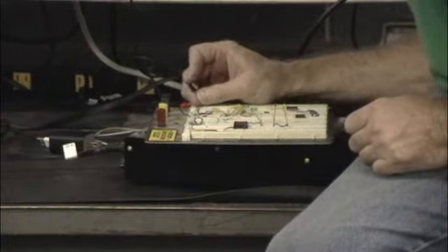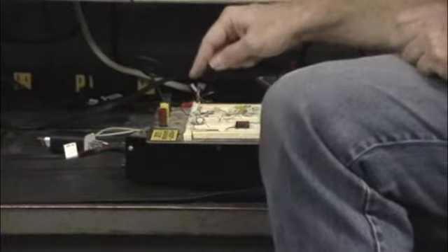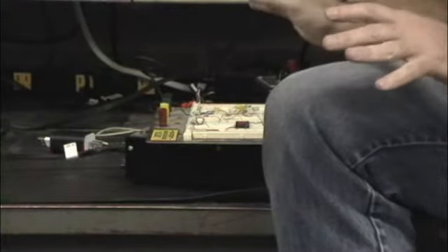Don't look directly at the capacitor. Don't stare at these. If you've got a problem on a board and it's drawing a lot of current, as often as not, it's a capacitor. And then you can look at these ones.